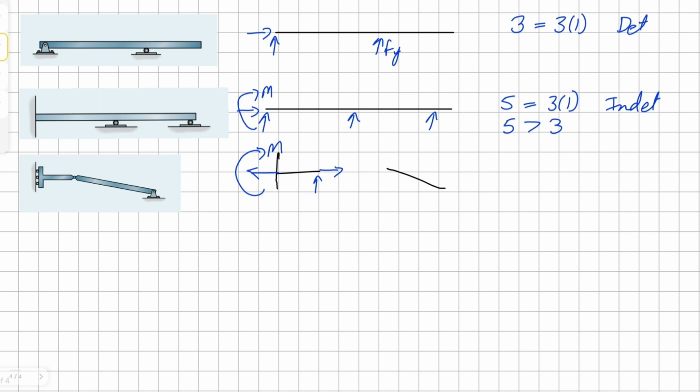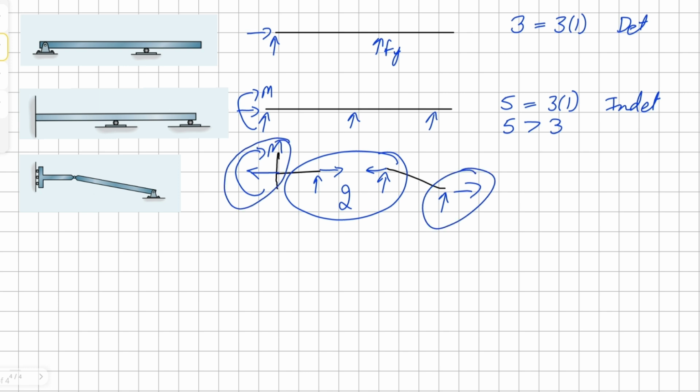The same thing on the other side for the other segment, there will be x and y components, and then again x and y components. So for this, these are just 2 reactions, being on opposite ends. And then we have 2 reactions here and 2 reactions here. In total, we have 6 reactions, and we have 2 segments. So this is our statically determinate structure.